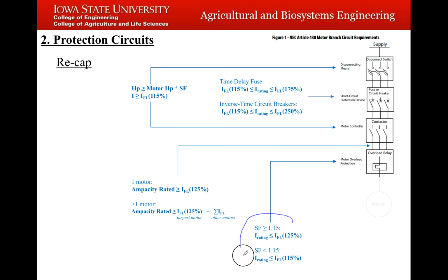When we talk about our overload relays, these are based off of the motor nameplate. So we look at the motor nameplate. For all other current and horsepower values, look at the tables.